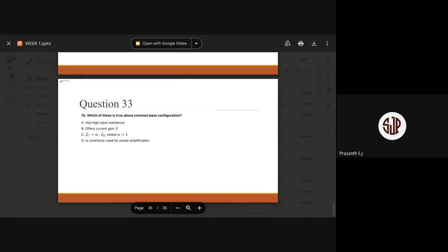Early effect is one of the non-ideal effects in a BJT. Normally in an NPN transistor, the BC junction is reverse biased, up to a particular extent. As we keep on increasing the reverse bias voltage of the BC junction, the depletion region across the BC junction increases, and after a certain point it reaches the base-emitter depletion region completely. That is, it occupies the base completely, and there will be no base region existing in the transistor.